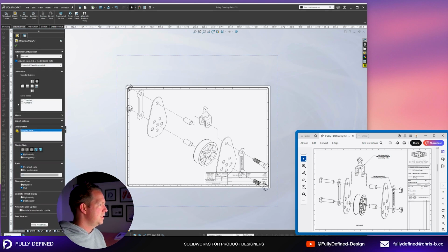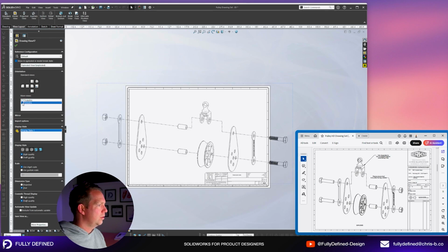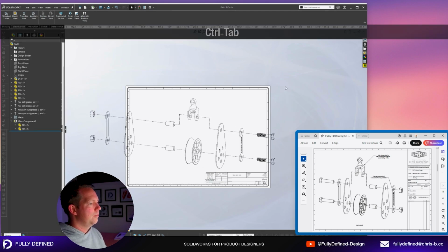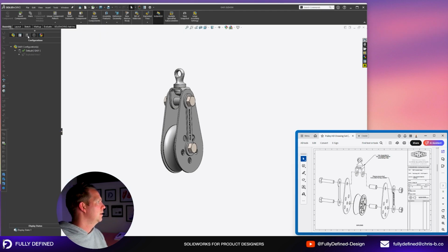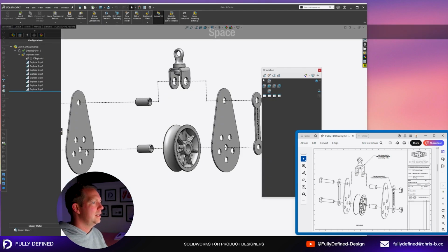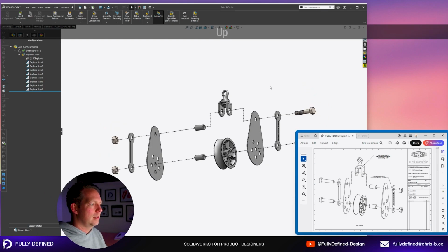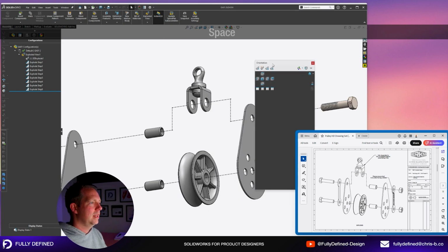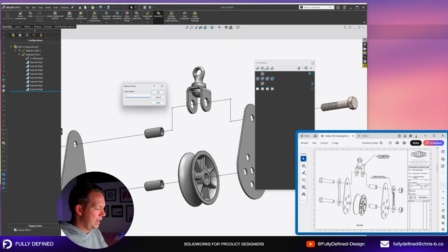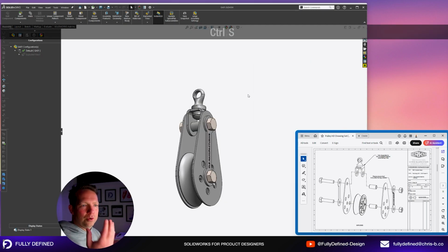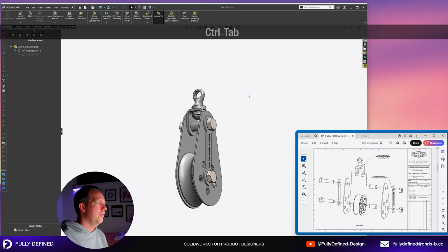Because if I click here on these standard views, I click trimetric or diametric, like maybe this is the one we will use, okay? But if I want to get really specific and do an exploded view here, let's say I want it to be just a little bit underneath like this. So I'm just using my arrow keys. I can press the space bar and click new view and I can name it. Doesn't matter if it's exploded or not exploded. That's independent of the actual drawing view.